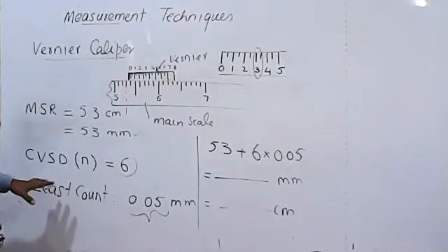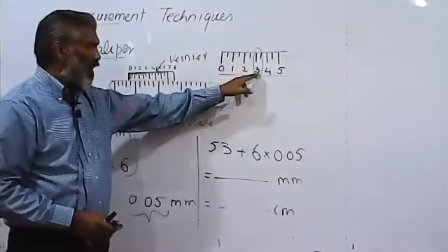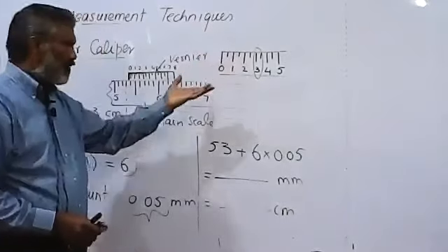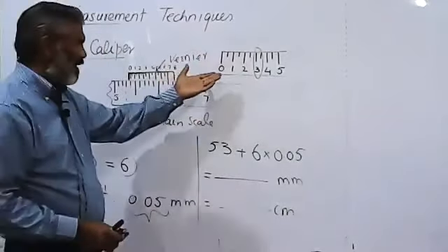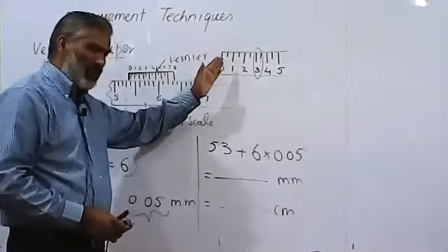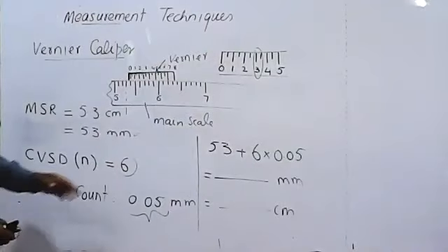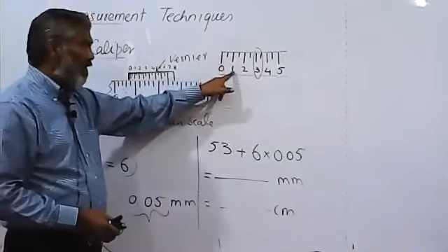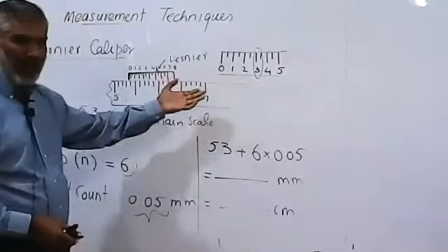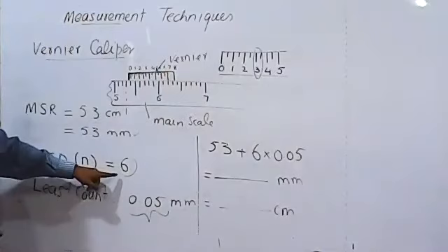And I emphasize again that it is not the number that you should be deceived by, because the instrument we have in the lab is of this type. In between each two divisions we have one more division that makes it more precise. So if it is division number 1 coinciding, it is actually the second division. So if it is the third division numbered there, it is the 6th.